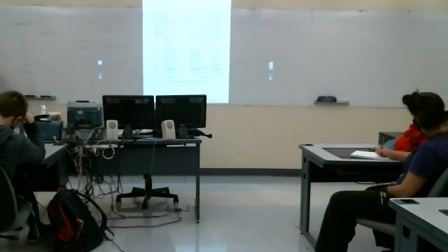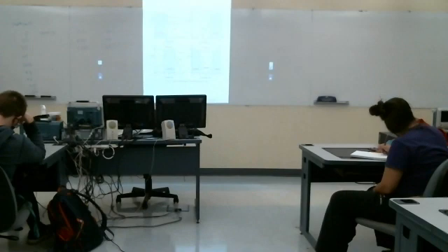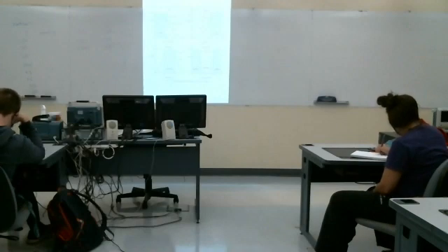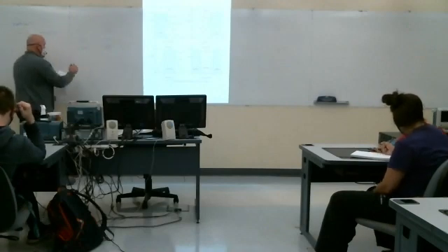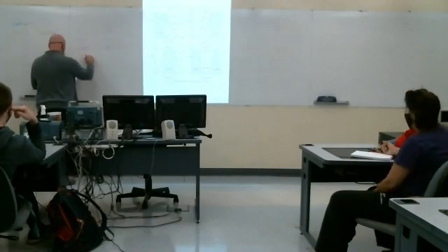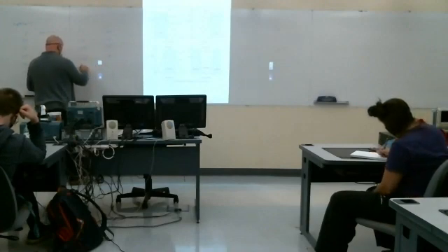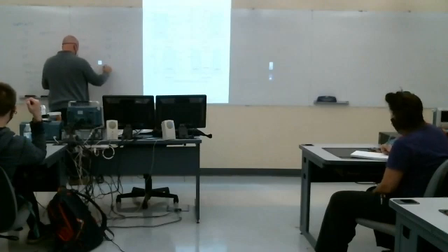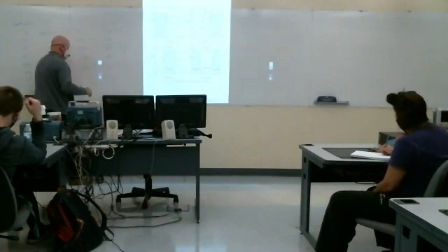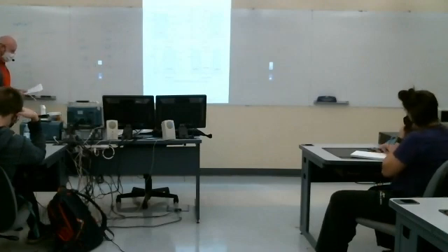It actually still follows the same rule. 0.001 is 10 to the minus 3, right? So 20 times minus 3 is minus 60. And 1 over square root of 2 is minus 3 dB. 1/2 is minus 6 dB, and so on and so forth.